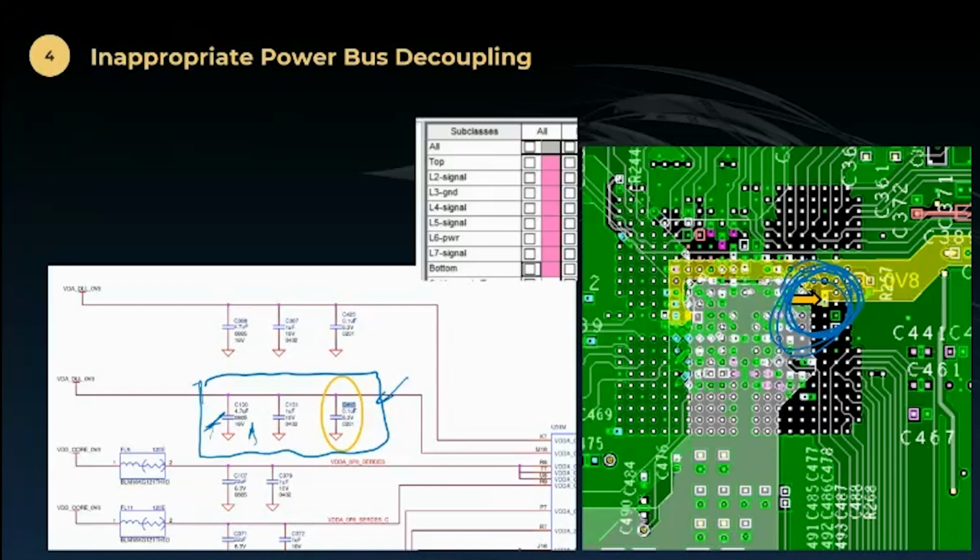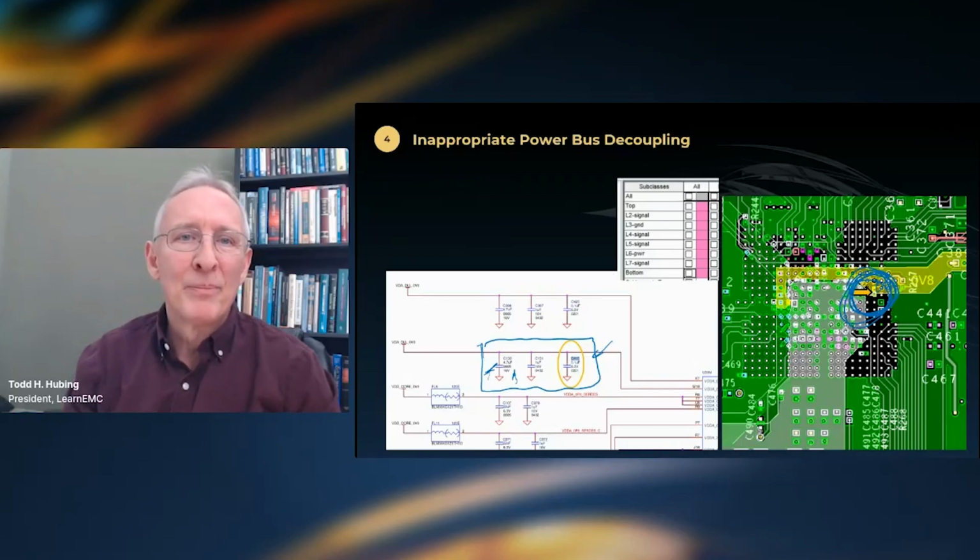And we're not seeing all of the ground planes. The ground is fine. There were several solid ground planes in this design. But the voltage plane coming over, the capacitor is hanging off the edge of the voltage plane. I see that all the time, and it just unnecessarily adds inductance to the connection. We should tuck that capacitor up to where it's solidly got both planes underneath it, particularly in an 0201 package, where the whole reason we use that package size was to get a low inductance. So it's not a terrible error, but it's not optimum.